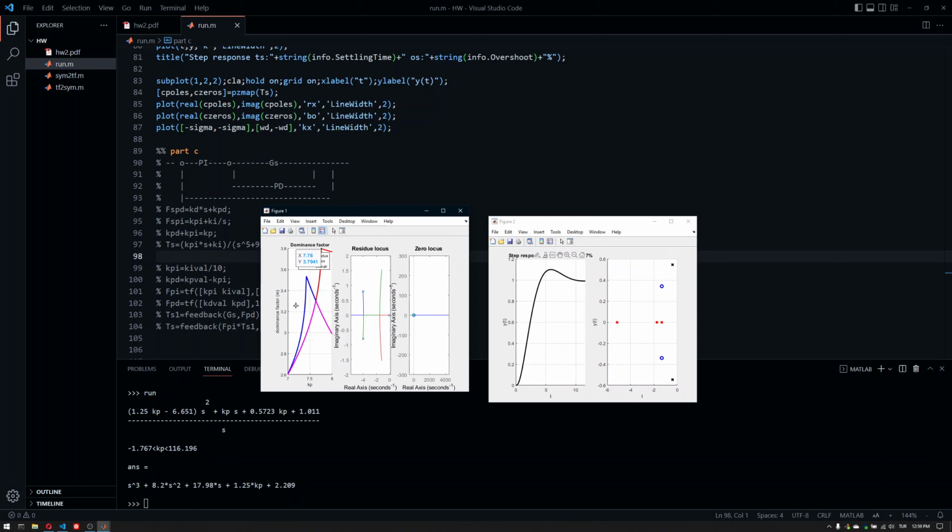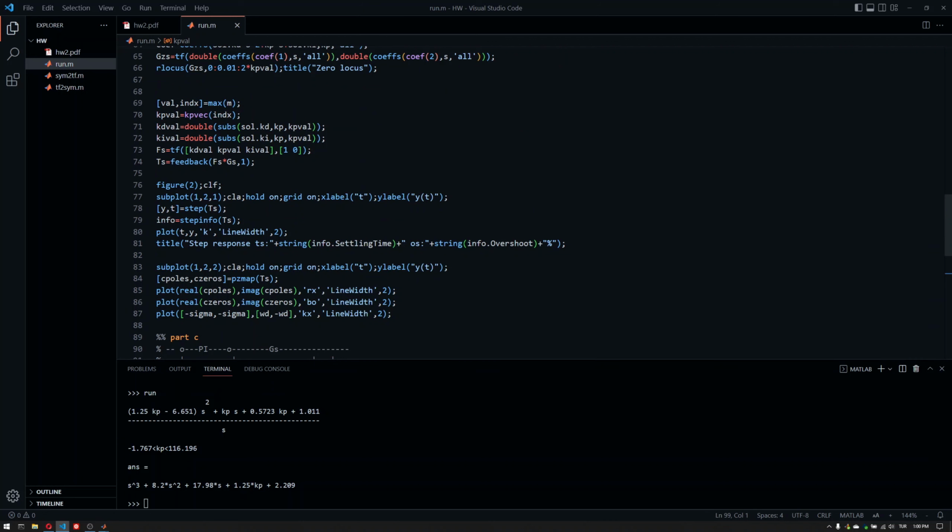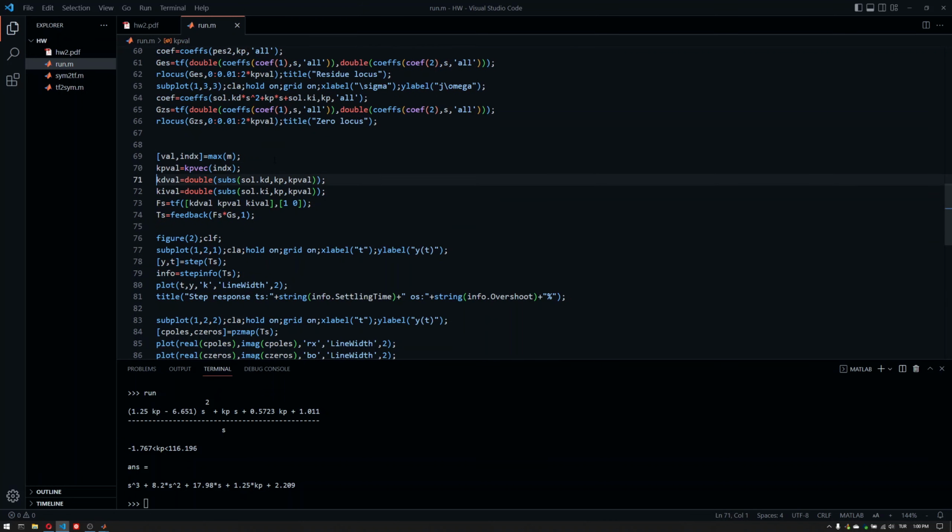So I don't have to push the zeros anymore. I can just use the best possible solution for the most dominant poles, not the zeros, or not overall again. I can just focus on the poles. I can push away the poles, and it should give me a better result. Now I can see here that 7.76 seems to be the solution that I look for.